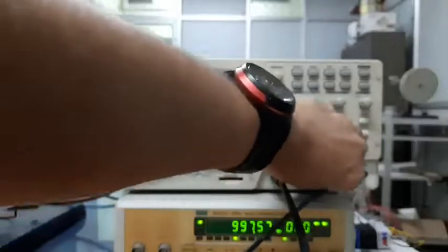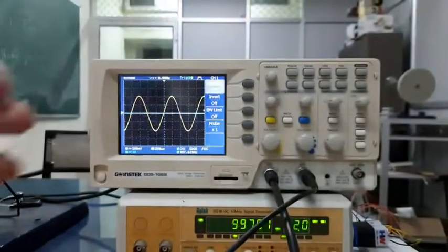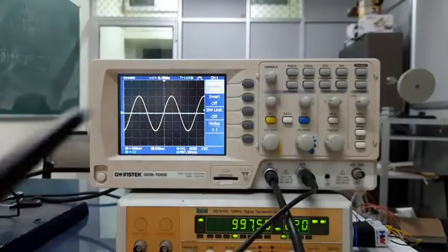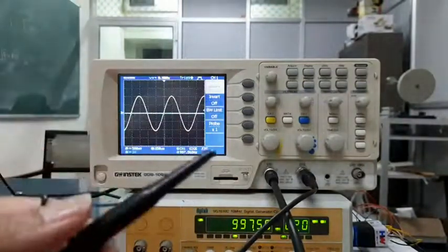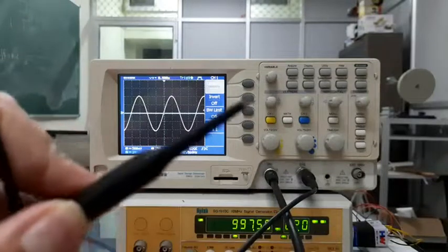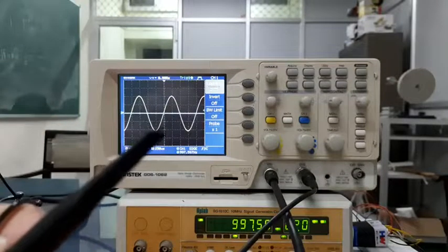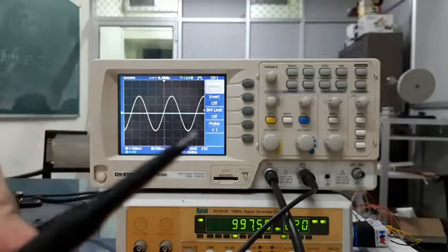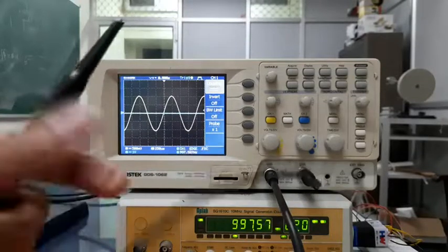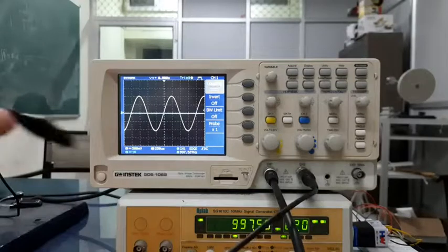And now on the breadboard you can use this probe connector to see the signals. Again, this hook is supposed to be used for the signals, right? And you should only use this hook for the signal because it is connected to the internal core of this BNC cable, coaxial cable.